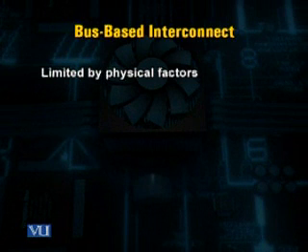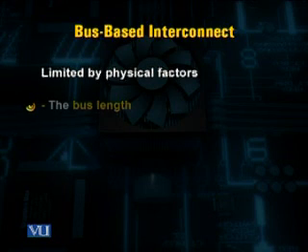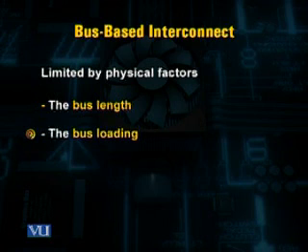However, the bus speed is limited by the physical factors such as the bus bandwidth, the bus length, and the bus loading. The bus loading means the number of devices which are being connected to a bus. These physical limits prevent arbitrary bus speed up, which make the bus design difficult.